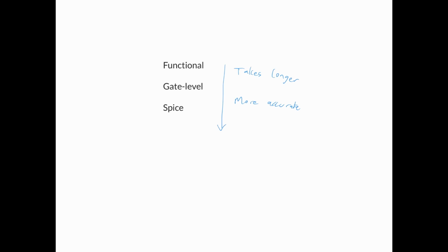The main reason I've shown you SPICE is because I believe it's very important to understand that while most of the time we work with zeros and ones, underpinning all of that are true voltage waveforms, and they are not ideal, and at some stage we do need to consider their imperfections. Perhaps even more relevant is that we have been discussing propagation delays and contamination delays, and even setup time and hold time, and it's through SPICE simulations that we can understand where these delays come from, and we will also be able to use SPICE simulations to see how a flip-flop can become metastable.